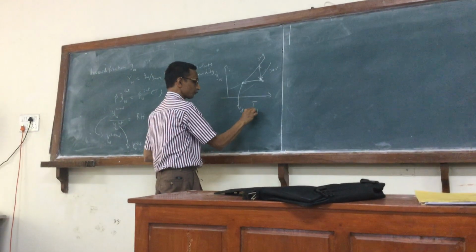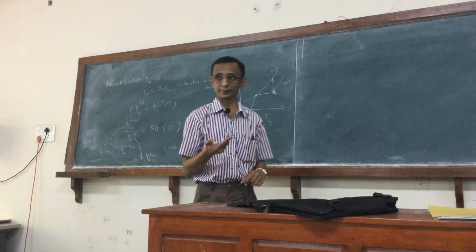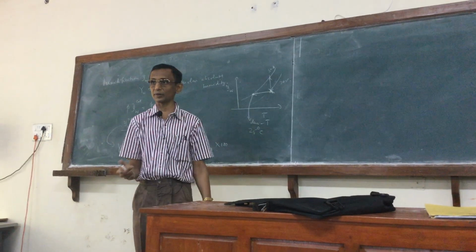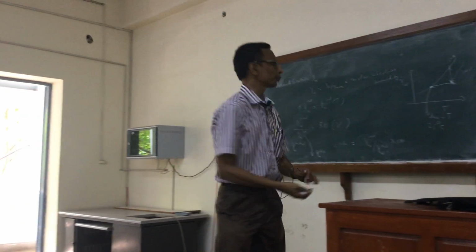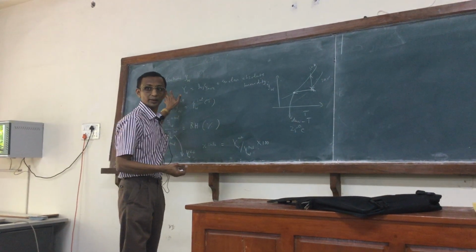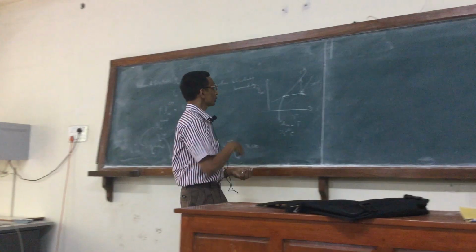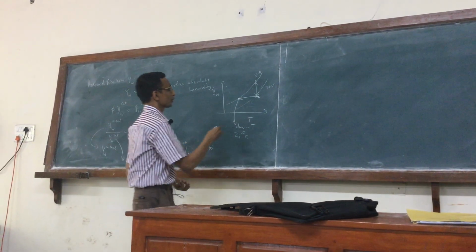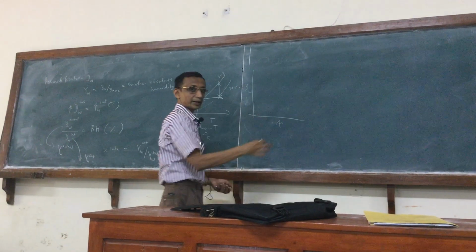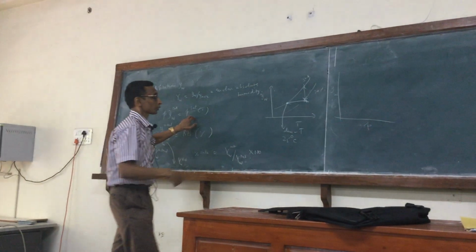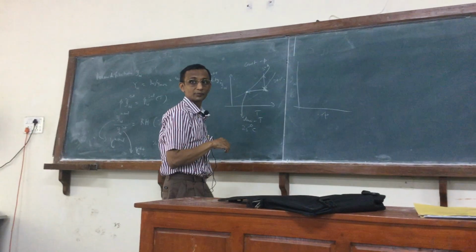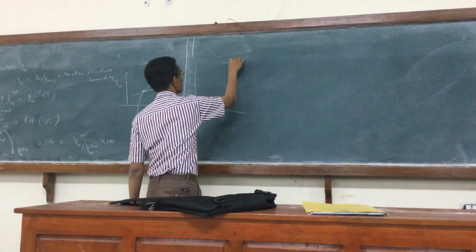In the calculation I did yesterday, the dew temperature turns out to be approximately 25 degrees centigrade. We saw how to do that. So this now becomes the saturation. I have to substitute that into this equation and find the temperature. And you can do the same thing in terms of pressure. This will probably be decreasing because YW is inversely proportional to pressure. So it's very important, this is at constant pressure, typically 1 atmosphere. This could be at constant temperature.